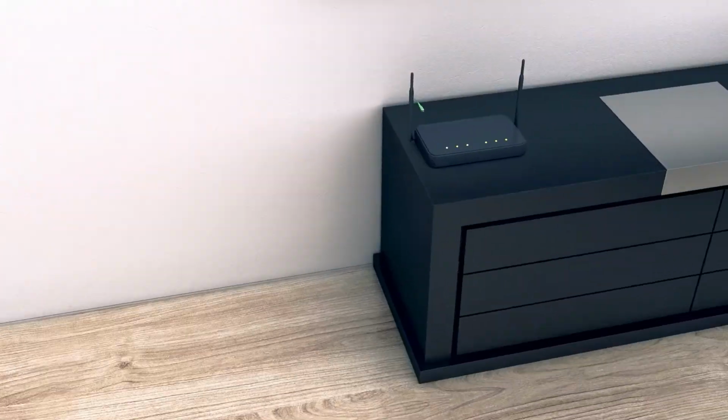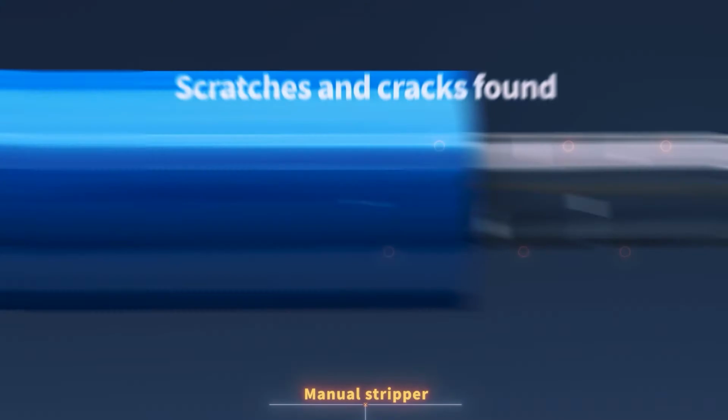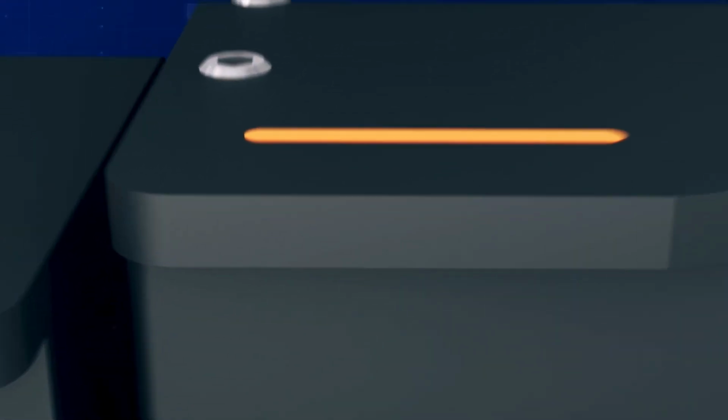With a compact, light, rugged design and a long-life battery, the KF4 delivers high-precision performance with electrode life up to 38,000 splices and rotating blade life up to 75,000 fibers. The all-in-one function of the KF4 splicer is patented by UCLSwift. This provides the best workability and convenience on poles or in limited spaces by integrating stripping, cleaning, cleaving, splicing, and sleeving functions into one splicer. The thermal stripper in the all-in-one system prevents scratches or cracks on the fiber that are usually caused by manual strippers.